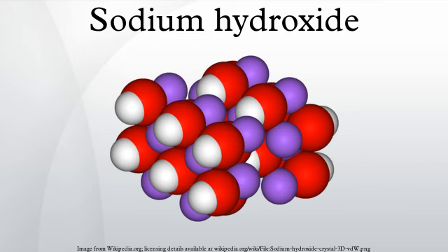A parts washer heats water and the detergent in a closed cabinet and then sprays the heated sodium hydroxide and hot water at pressure against dirty parts for degreasing applications. Sodium hydroxide used in this manner replaced many solvent-based systems in the early 1990s when trichloroethane was outlawed by the Montreal Protocol. Water and sodium hydroxide detergent-based parts washers are considered to be an environmental improvement over the solvent-based cleaning methods.